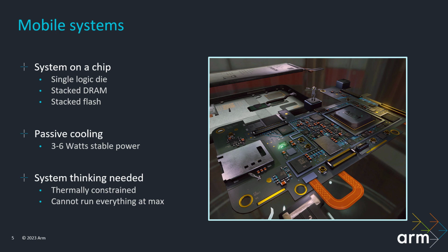What makes mobile a really fun optimization target is that you have to think holistically. The power that we're generally constrained by comes from the entire system on a chip: CPU, GPU, display controller, memory bandwidth, and so on. So if you're trying to fit inside a thermal budget, all parts of that system have to be working well together.